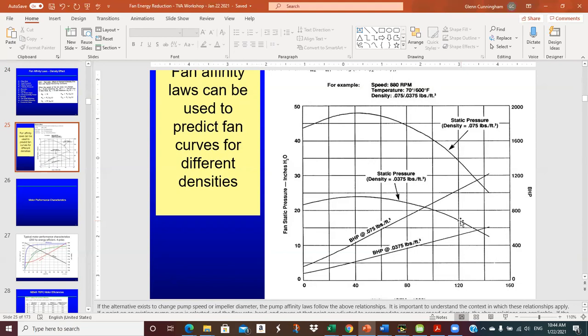But yeah, soft start, that's a good point. And not even a soft start, right? Soft starts won't start everything that a drive can. So you have to be real careful between all three fan starting methods. Soft starts are limited. Drives can typically start the biggest loads. Direct online, you're limited by your motor and your distribution system. Agreed. Very good. Thanks for those comments.